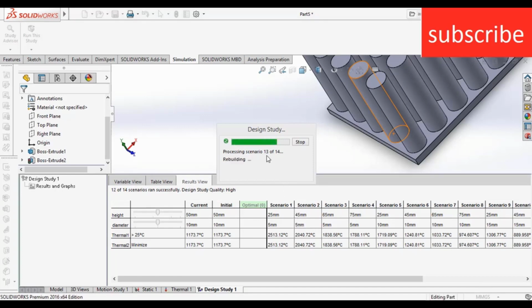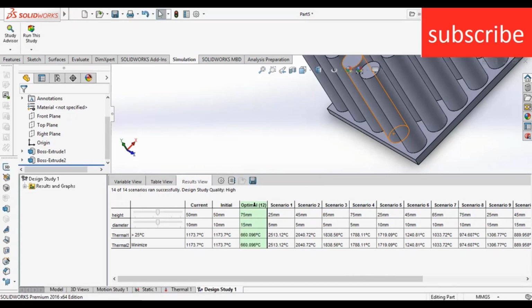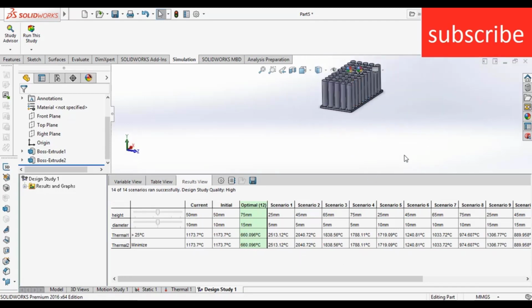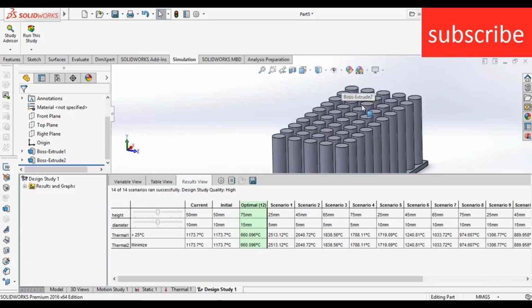As you can see, it is currently on the last one, just one is left. After that it will finish, 13 of 14, and here it has done the simulation. Here you will see that when my height is 75 mm and my diameter is 25 mm, I got the minimum values. So this is how a design study is done in the case of thermal.